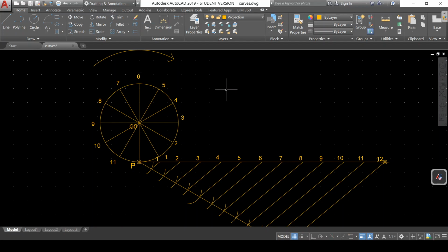So gradually, as the circle rolls 1/12th revolution by 1/12th revolution, this P is moving, advancing on the circumference, and lastly when one complete revolution is over, P will again touch the ground here at this location, and this center will traverse along a straight line here, C0, then C1, C2, then on this C3. So let us draw those projectors for all the points for these circles, horizontal projectors, and then trace the path of P on those projectors. So let us do that.